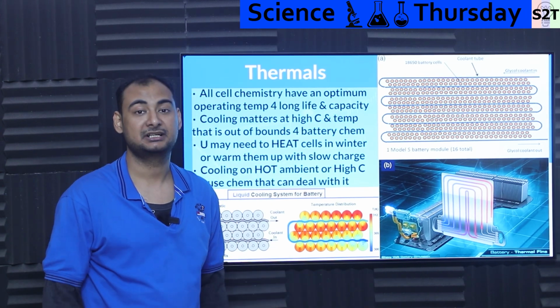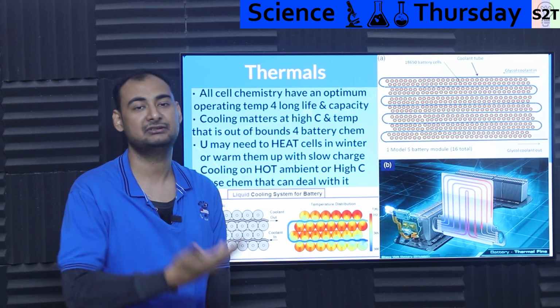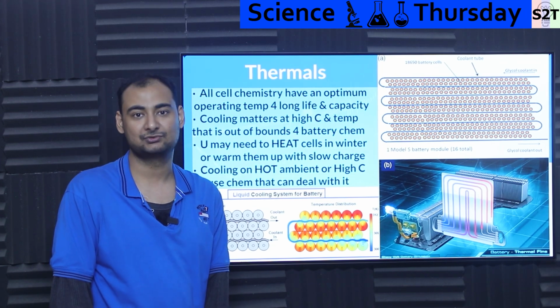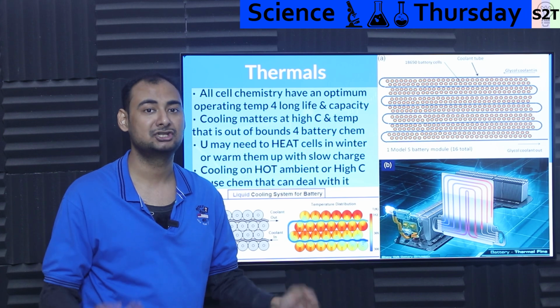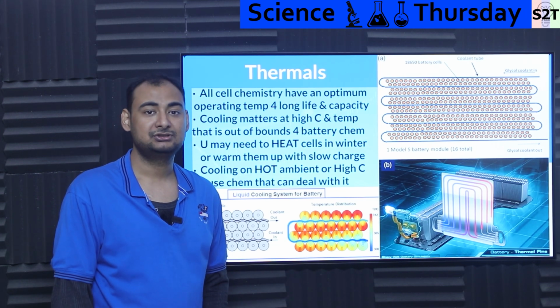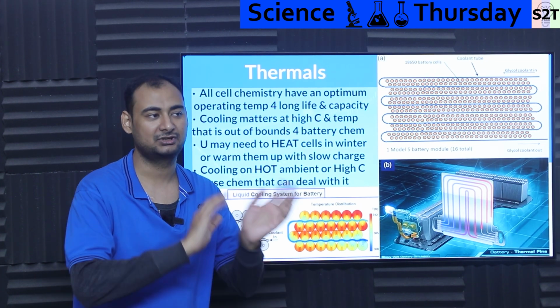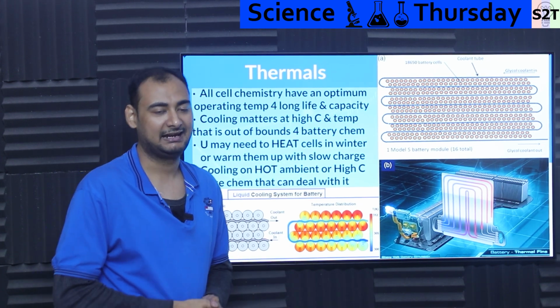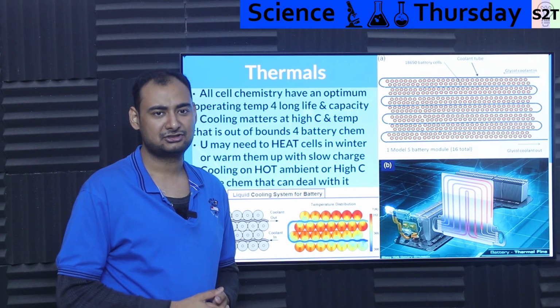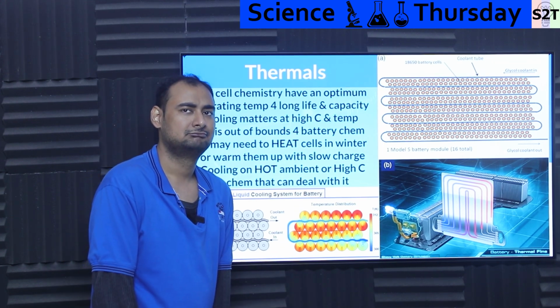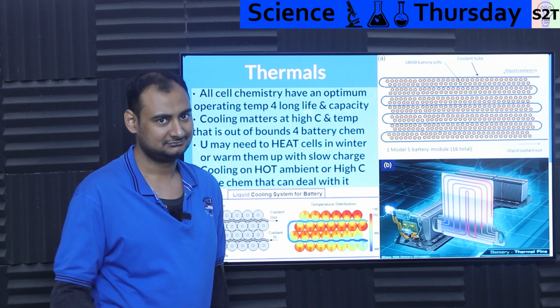Again, if you are making, let's say, a military vehicle, you do not want the complexity of a heating or cooling system, so you may choose that. The penalty would be that the capacity would be much lower. The benefit would be that those chemistries can handle surges. You may not even bother to put in a BMS, you'll just put in a balancer just to make sure. Your charging current is like, I'm going to give you 500 kilowatt, and it's like, meh. So that can be done.